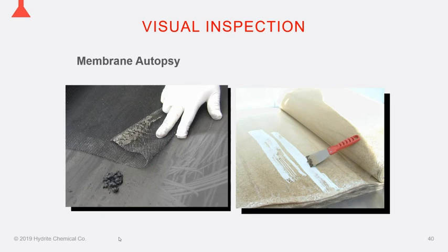So if this is a membrane that has been fouled, a lot of times one of the diagnostic efforts that we'll do is we'll go ahead and take some of that soil off, test it in a couple of solutions like that former slide with the protein was showing, in order to see what dissolves it. And again, let me just repeat, this is going to be the fastest way to get information on what the foulant is and simultaneously come up with a solution based on what removes it the fastest.